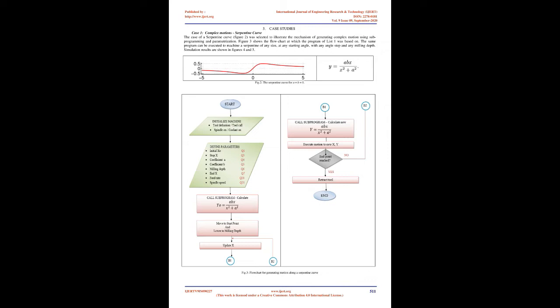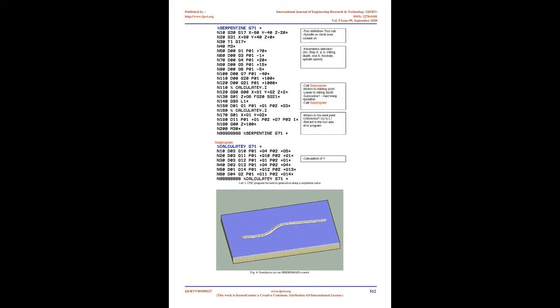Parametric programming constitutes an innovative programming technique of G/M code programming language. This innovation is not well known, which is unusual because of the fact that it simplifies the CNC procedures dramatically, lessens the user's dependence on CAD/CAM and contributes to bare minimum cycle time. As production quantities grow, every second of program execution time becomes more critical. An important factor that minimizes the cycle time is how the program is formatted.